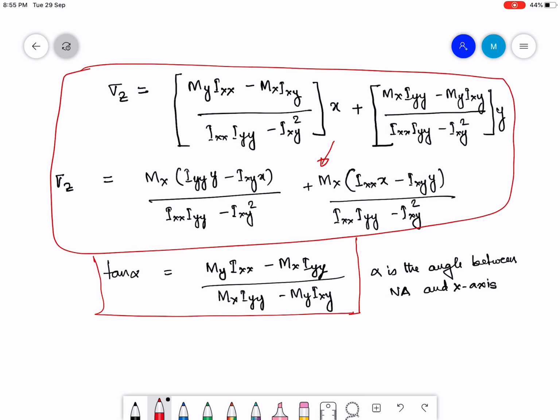All this while, when we were dealing with unidirectional bending, we always thought that the neutral axis just depends on the property of the cross section. But now we see for bidirectional bending, the neutral axis is always going to pass through the centroid, that's for sure, whatever be the applied force. But the angle that the neutral axis makes depends on the applied force. This is a bit counterintuitive, but this is a good takeaway from the derivations that we have done.